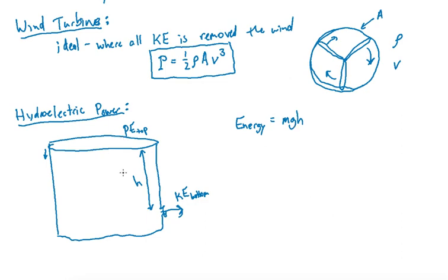If this is dropping really fast, like if this was a really skinny container and the water was dropping out real fast, then this wouldn't hold anymore. This little top here has to basically not really move very much. It has to stay at that same depth, or it gets a lot more complicated.